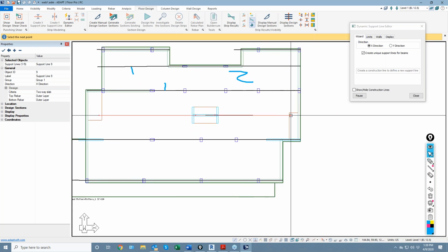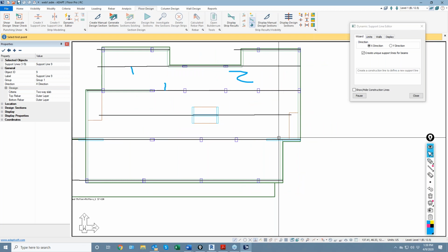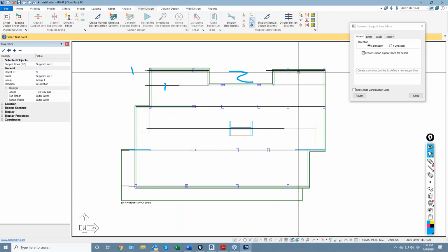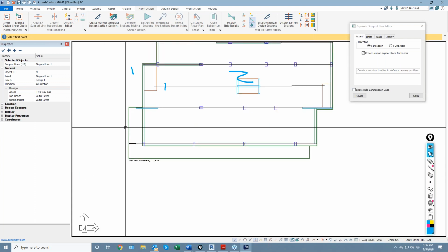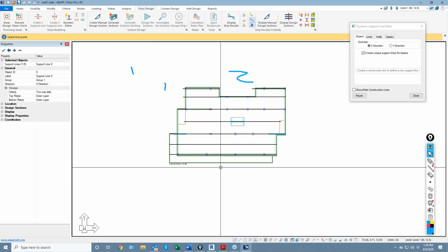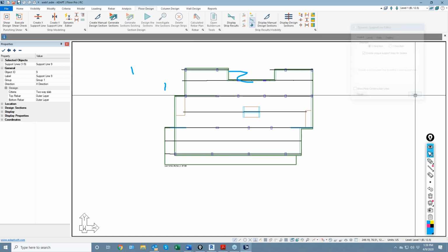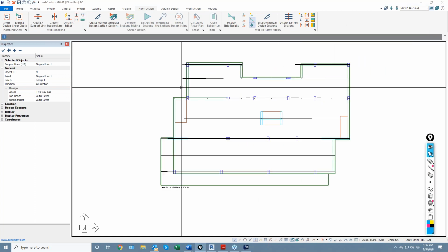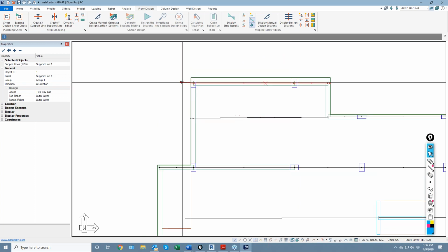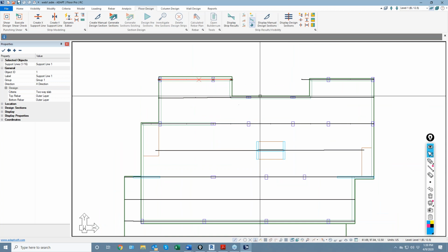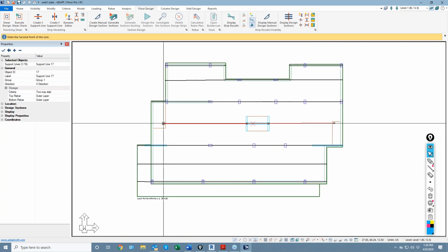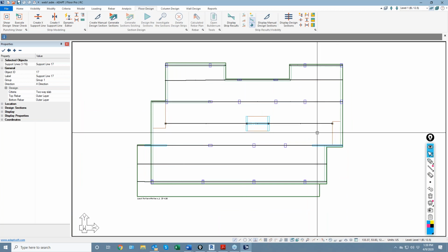Okay, so I'm going to model a middle strip there. We already have this middle strip here. You know, you could model another strip here. I'll just leave it as is, and then down here we're going to model a strip along this path. So I'll just do 2 points that passes through that location. I'm going to close this. And if we wanted to clean up these points on the perimeter, I could always just bring those back to face of slab. We don't need to, but just for sake of cleanliness in terms of the model, we'll go back and adjust those. I could adjust these back to the face of the openings.